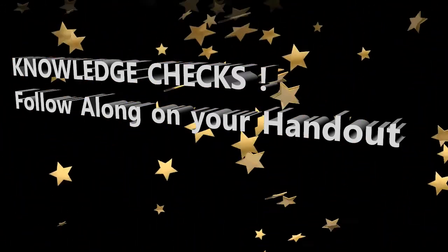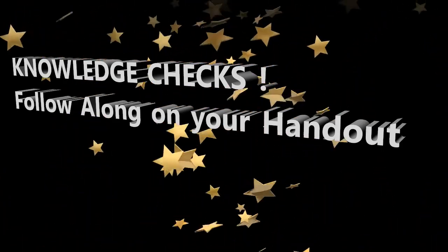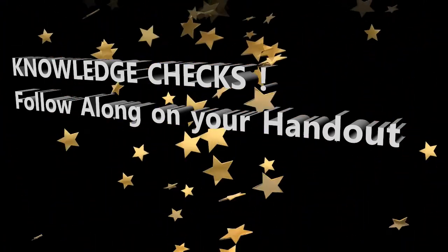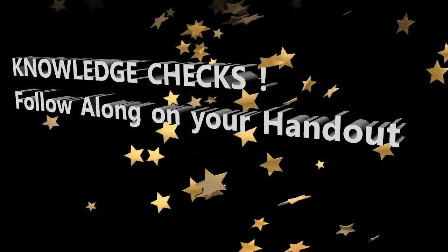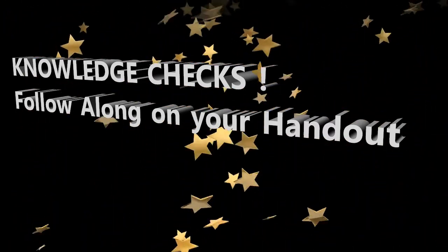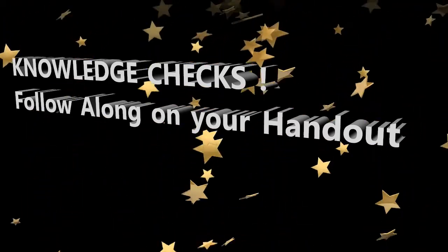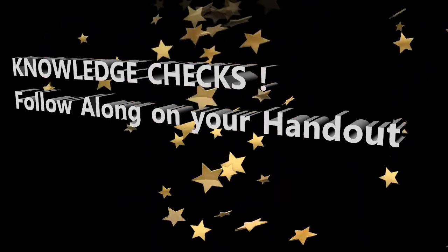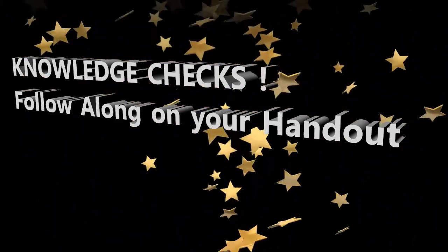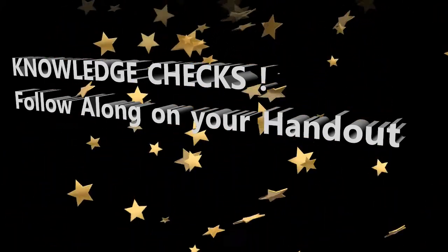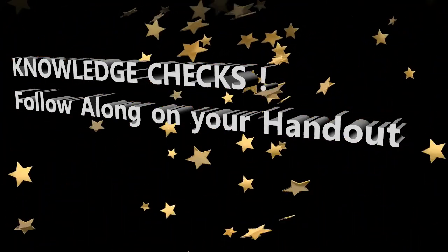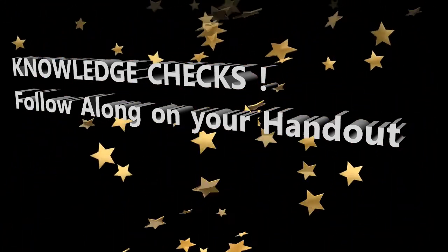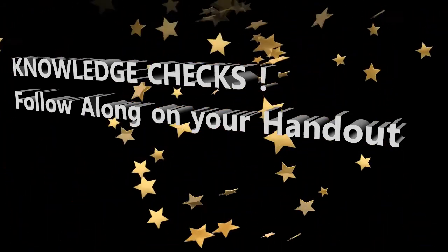All right, well, what is one condition that can cause a hot start? I mentioned hung start, and defining hot start, I hadn't done that yet, but here you're going to get it. Think of hot start, think of hot fuel, because it just means you have too much fuel in the combustion chamber, and at the same time, the engine RPMs are just not up to speed. So what is one condition that can cause a hot start? Is it low starter air pressure or high starter air pressure? Okay, it's low starter air pressure.